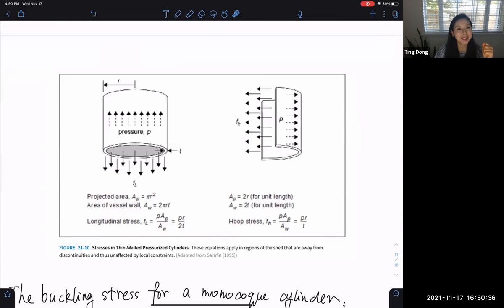Because a lot of times in my FE class, students don't do the preliminary analysis, the hand calculation, to know the approximate range, and they go into Abaqus directly, and they can generate very beautiful contour plots of the stress level and everything. And they feel, okay, great, we generated a very beautiful result, and they consider that the exact result. That can cause a lot of problems, because a single mistake in the input in Abaqus can generate a very weird result.